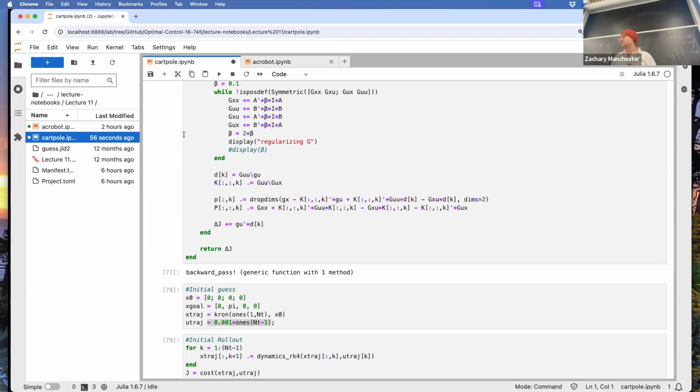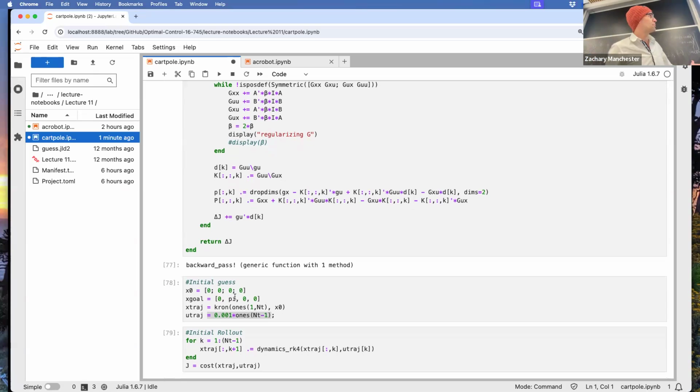Yeah. Could you do something that wasn't the pendulum straight up, like at an angle or something? Is that going in and changing the terminal terms? So first of all, that's not an equilibrium point. So you can't actually sit still with the pendulum over there, right? Because it's underactuated. You could do some weird thing where you were moving, accelerating constantly, but that doesn't quite work, right? You could get it to some angle instantaneously at zero velocity at the end. And if you want to do that, what you would do is go change this X goal. So you can make that anything you want.